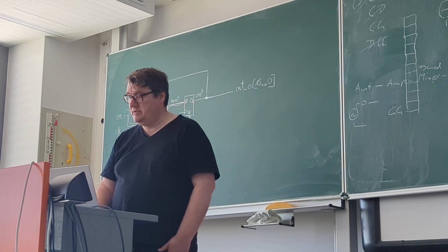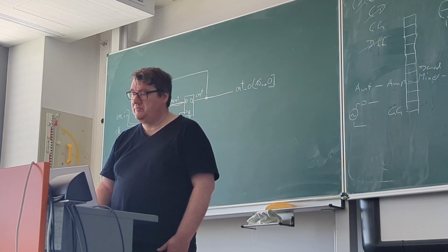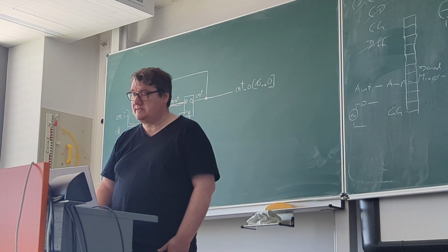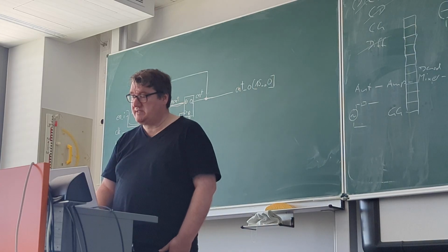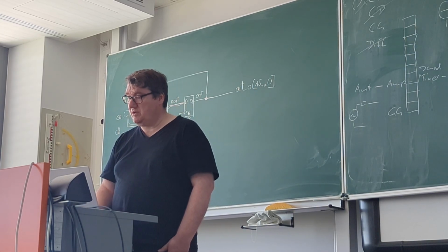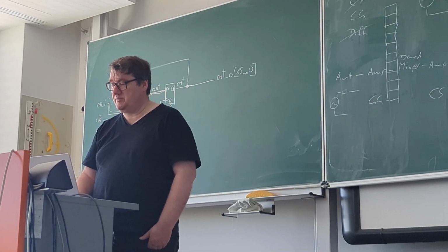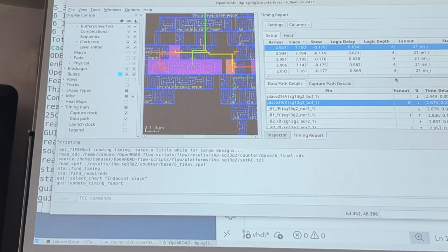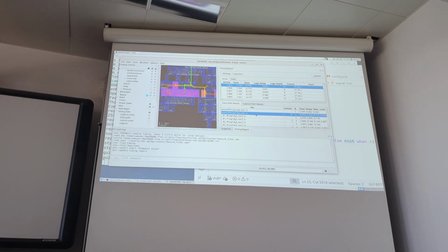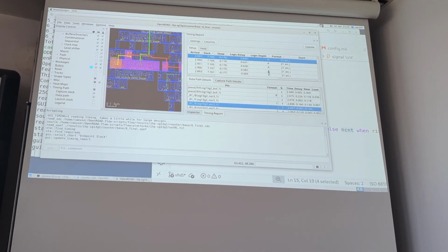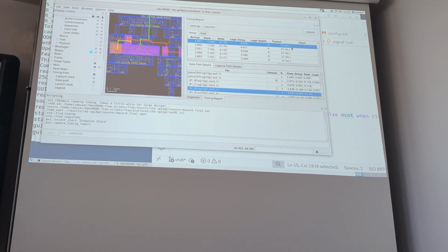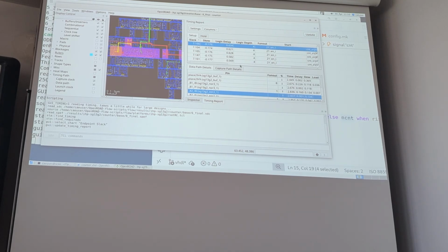The arrival time is 2.9 nanoseconds after start. Required time is 10, so we have really a huge slack here. The logic delay is just 600, that is the delay from these gates here. The logic depth is 4, but this is the critical path at the moment.